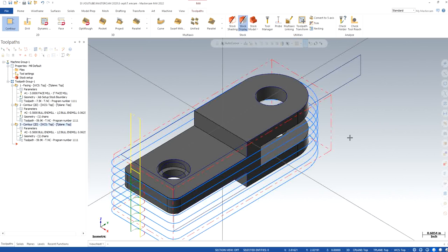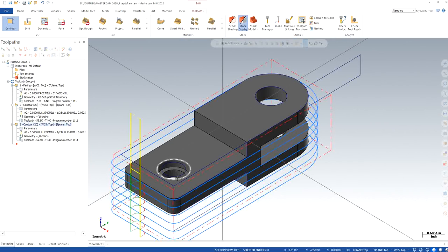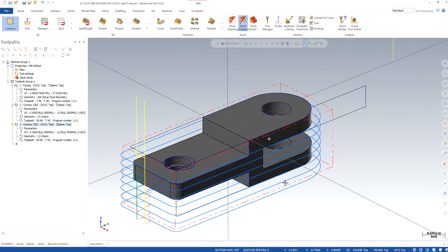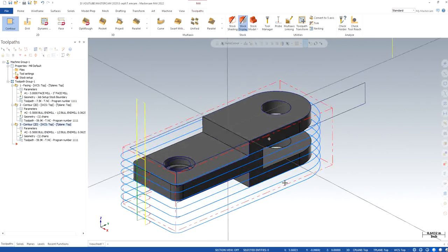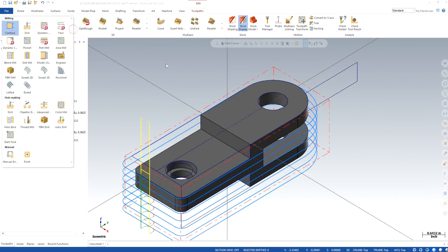That's what I can start with, obviously, because right now we are on this level, and going all the way through that dimension in the very first operation is going to be really too much for any part. So what I will do is I will simply make a center drill for both of them first.